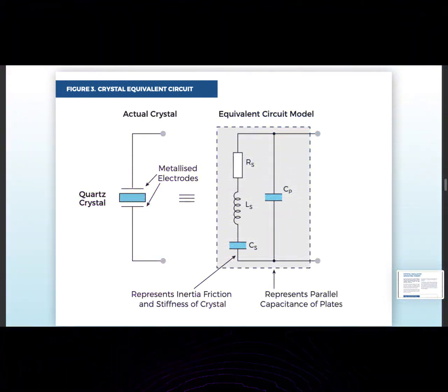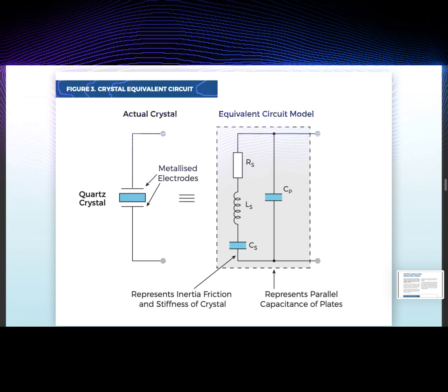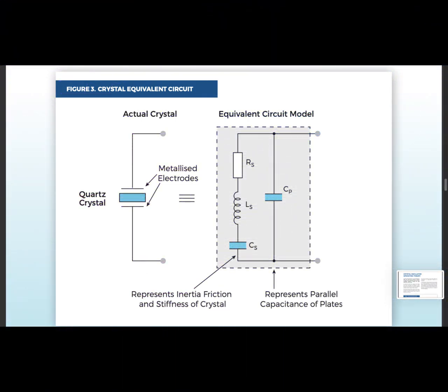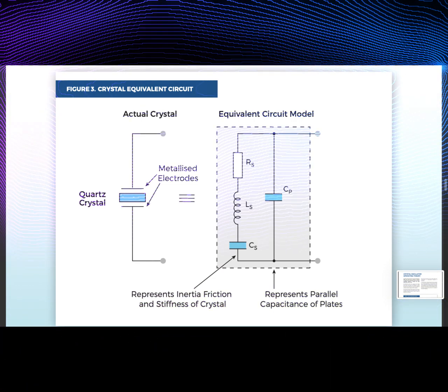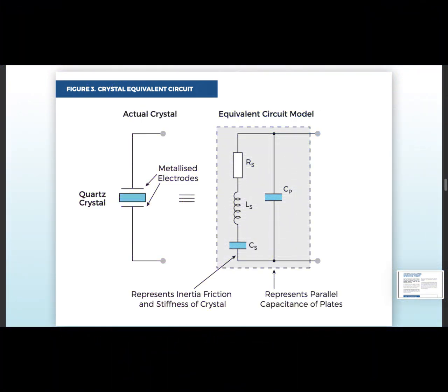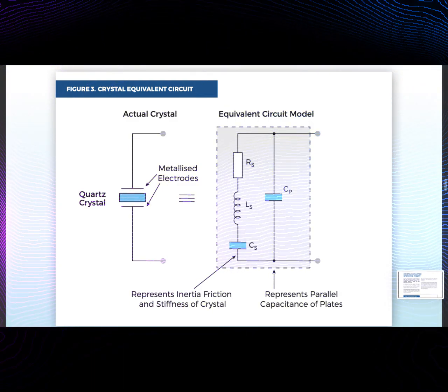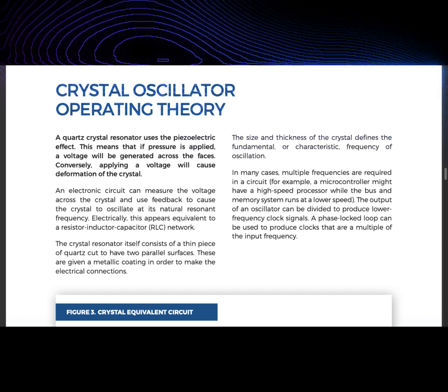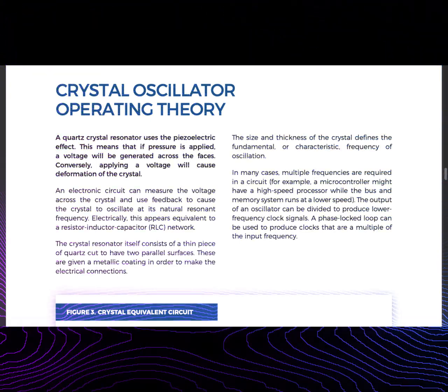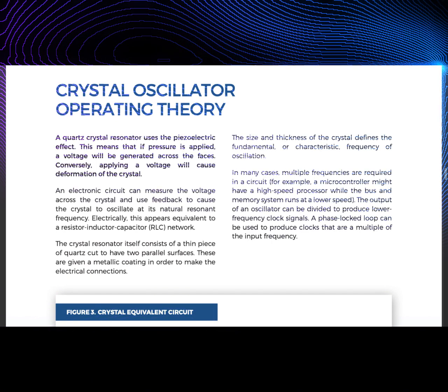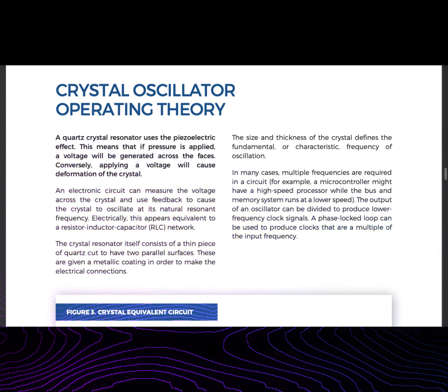The limited supply and the high cost of pure natural quartz have resulted in the development of a synthetic quartz manufacturing industry. Synthetic quartz crystals are produced in vertical autoclaves. The autoclave works on the principle of a hydrothermal gradient, with temperatures in excess of 400 degrees Celsius and pressures exceeding 1,000 atmospheres.